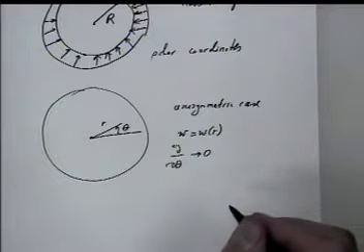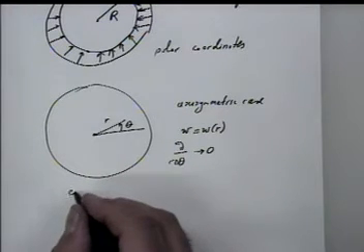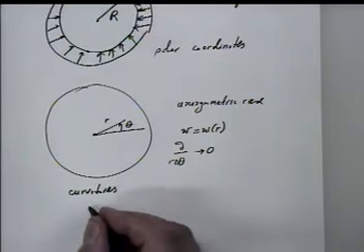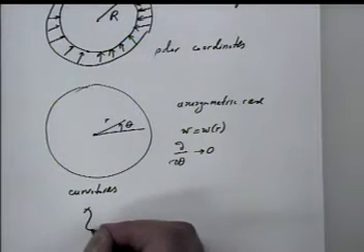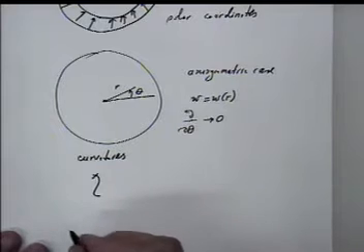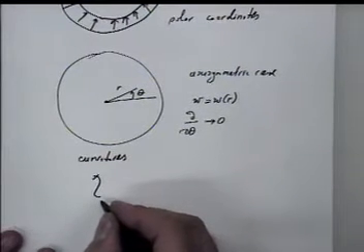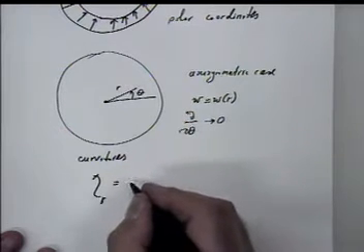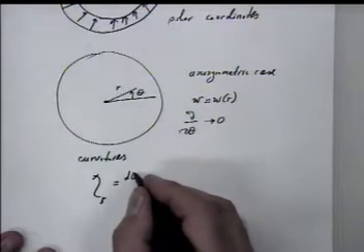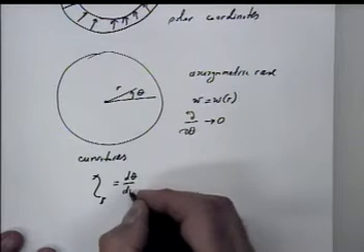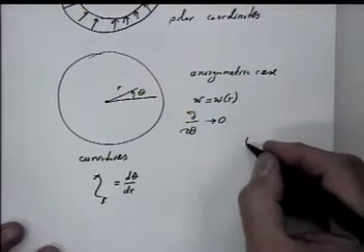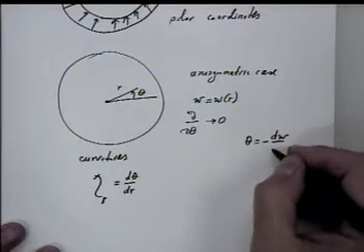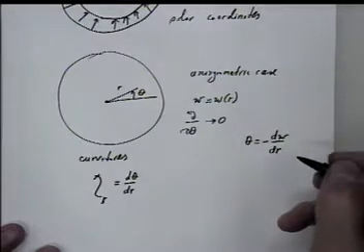So we have then curvatures. And these curvatures are denoted by Greek letter chi. Okay? So there is this chi r in radial direction. That is actually d theta dr. Theta is a negative slope, minus dw dr. That is a notation.